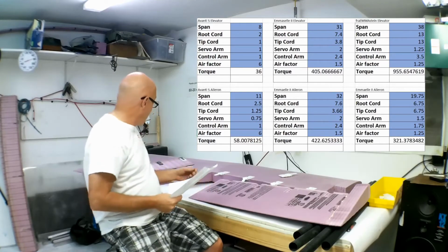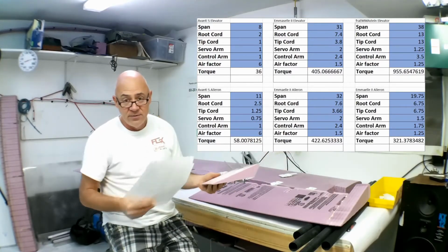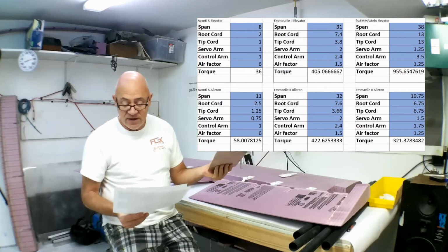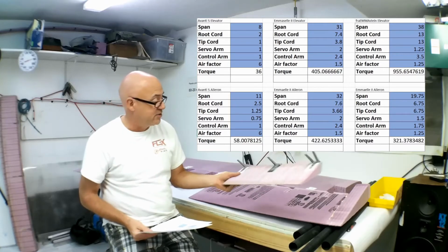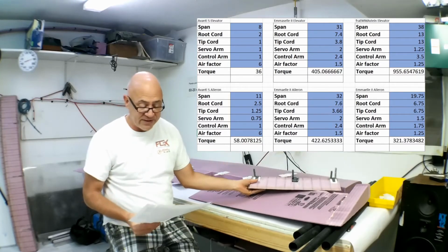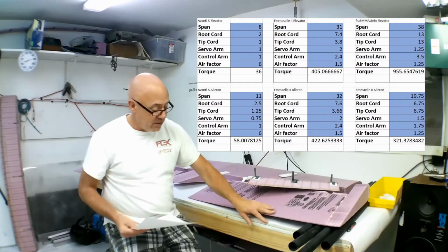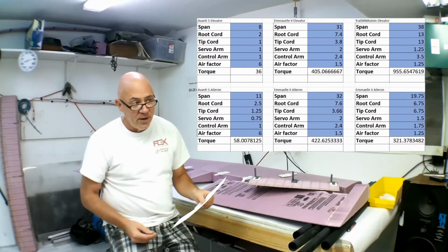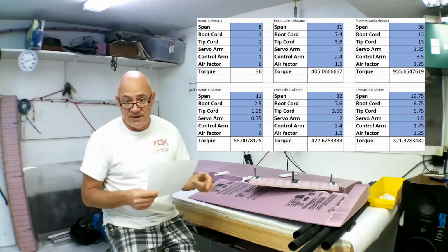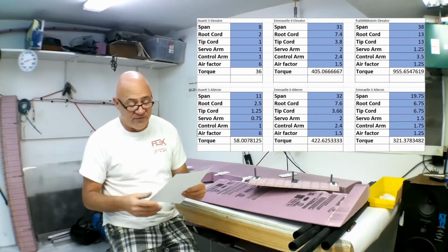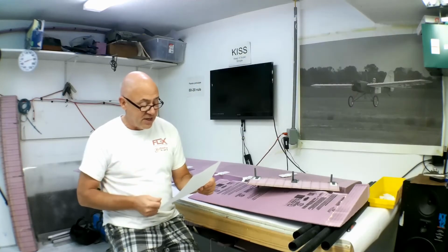If you look at the aileron, which is this little guy, but it still has a long cord to it, this is going to need 321 ounces. And I've got a couple of 425 ounce servos, so 1 of those will be on this. But when you're thinking control surfaces, you've got to think about the torque needed to move them. Flaps is the same way. You can put flaps into this little calculator up here, and it'll tell you what your flap torque needs to be. So now we're going to talk about the horizontal stabilizer.